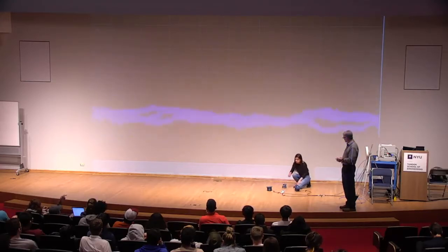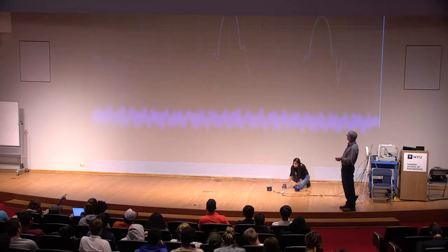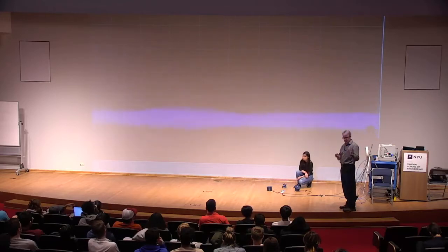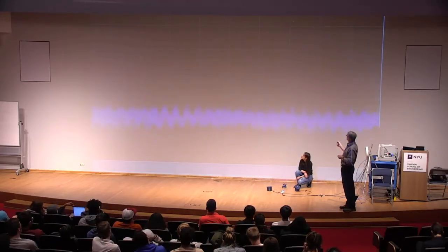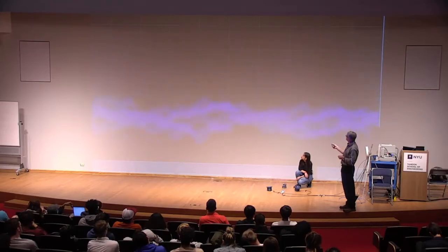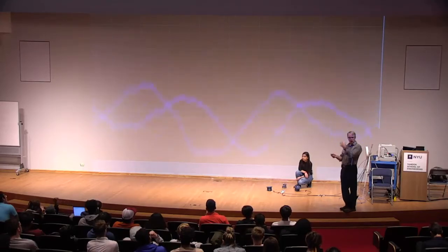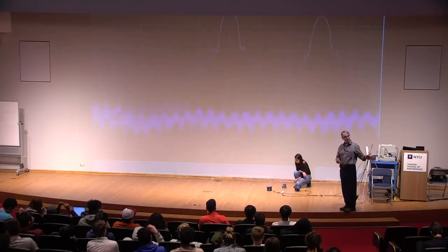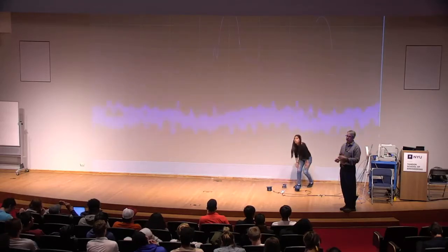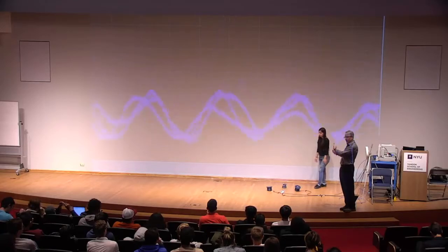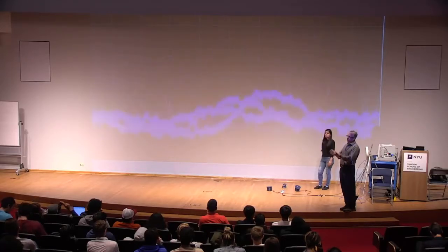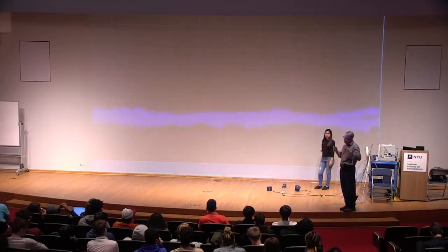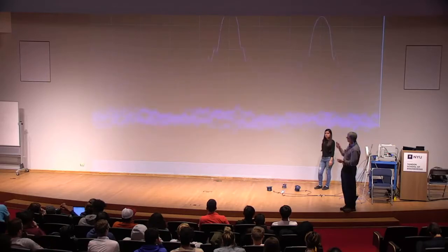Now let's go into the mode where they're simultaneous. Both of them are popping up at the same time, but I can design an electronic filter and filter out the 8 kilohertz. I can actually have a device that removes this energy, and I just focus on this energy. What we're looking at here is a mathematical formula called the fast Fourier transform. It takes time waveforms and very easily mathematically changes them into frequency. Then I can give this to the brains of the outfit, the microcontroller, and say, you now filter out and just don't even think about the 8 kilohertz one. Only focus on the 5 kilohertz and use that to drive your motors. So that's how this thing works.